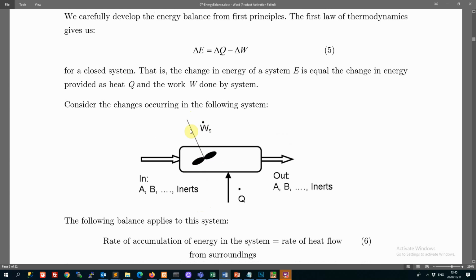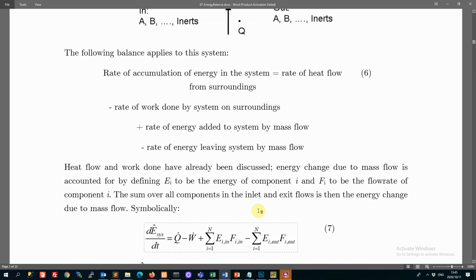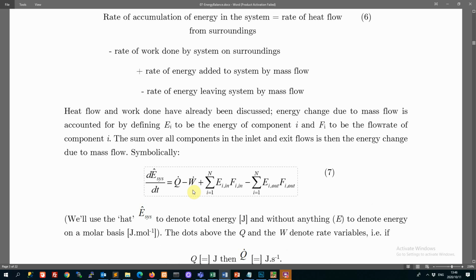And here, again, we are adding mechanical energy to the system. So you've got out here a motor which is connected to a power source, and so that power is driving this turbine, and that's causing our fluid to be flung around faster. So that's a direct input of energy also. And again, that has nothing to do with the energy due to reaction here. It has nothing to do with the energy here or anything like that. So this is an additional source of energy into the system. So that's the work part of it.